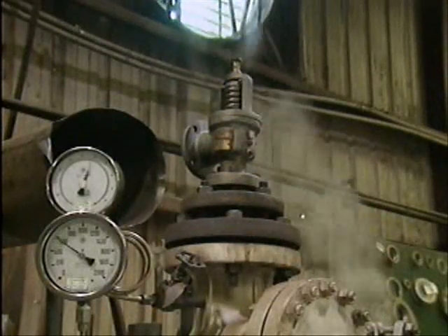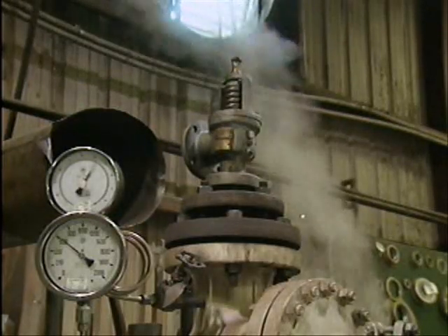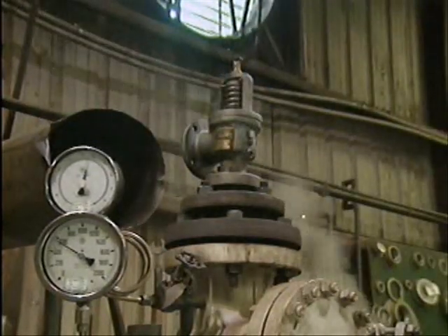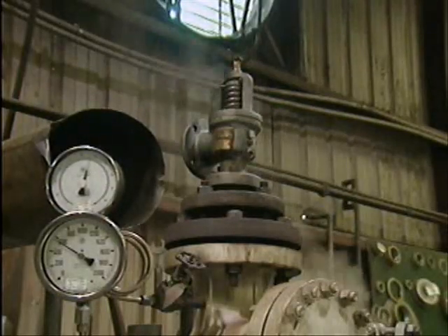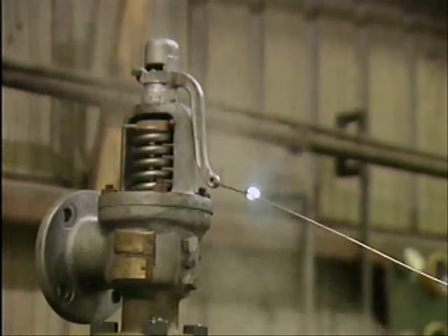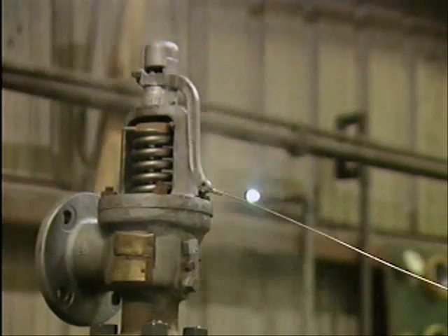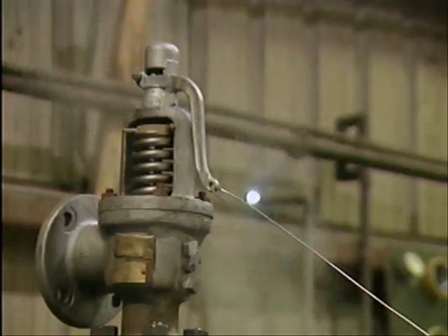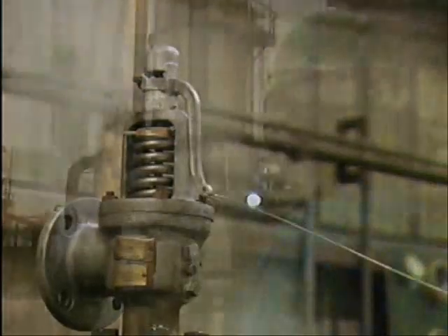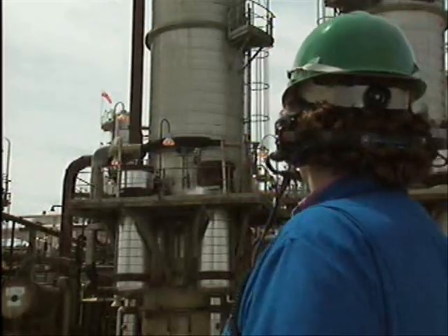An external inspection may reveal that a valve is leaking between the disc and the seat. This could occur if the valve didn't reseat correctly after the last time that it popped. Or it could be caused by foreign matter, such as ash, dirt, or rust particles trapped between the seat and the disc. In many cases, you can correct either of these 2 causes of leakage by manually lifting, or hand lifting, the valve. Hand lifting clears foreign matter out of the valve and gives the disc a chance to reseat properly. But anytime a safety valve is lifted, there's a corresponding drop in system pressure.